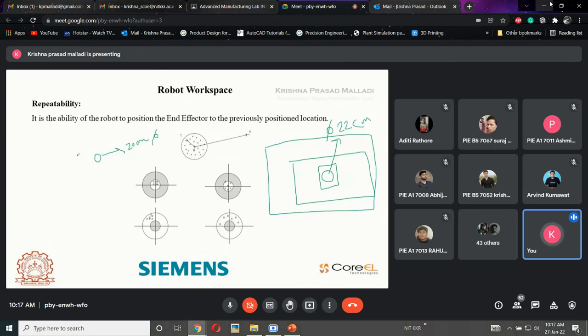Now the robot is picking without having any accuracy. There is no need of accuracy in this application, because in this region the part comes anywhere and the robot will pick it. There is 50 centimeters of tolerance, because of which accuracy is not needed. Whenever there is a part, the robot will pick because of the tolerance.